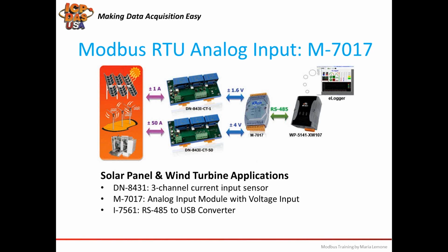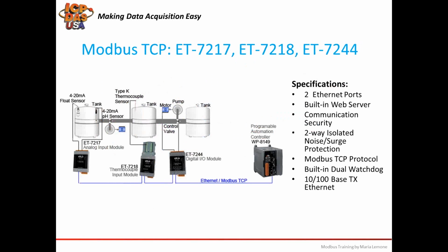It supports Modbus. We provide free eLogger software that allows you to set up simple control, monitoring, and data logging applications. Data from the WP5141XW107 can be sent back to a SCADA system over Modbus TCP.